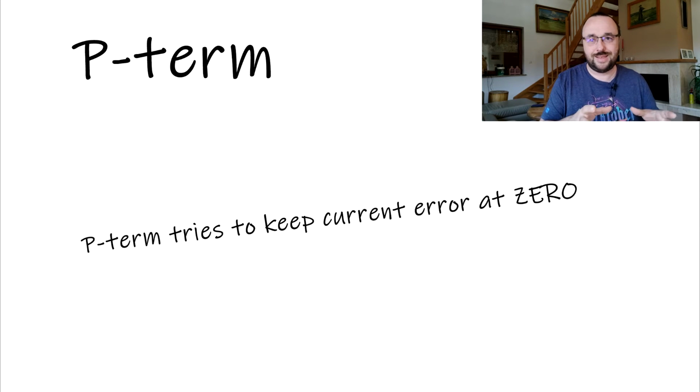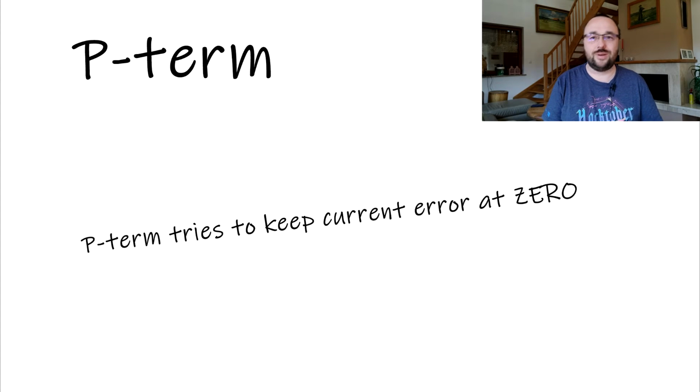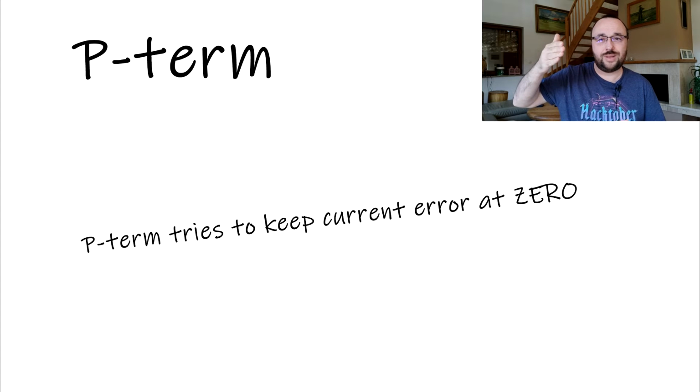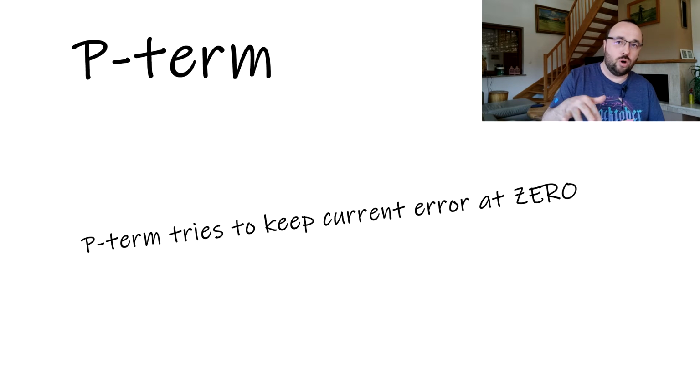If the P gain is too low, then our system, in our case the multirotor drone, will not be able to really keep current angles and will be wobbly, like a drunken sailor. If, however, the gain is too much and the response of the system is too high towards the demands, it will be overshooting, then overcorrecting. It will go into this characteristic, relatively high frequency oscillation. So, not enough P means that we are wobbly and not able to keep the correct state. Too much gain on the P term means we are going into oscillation.